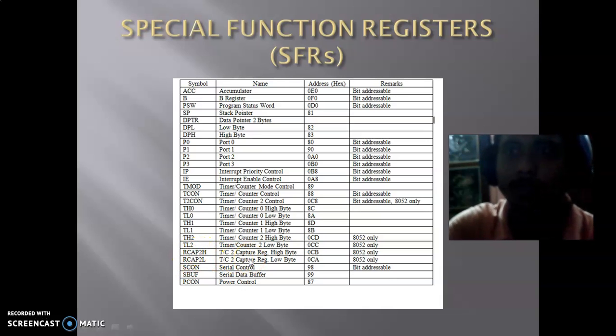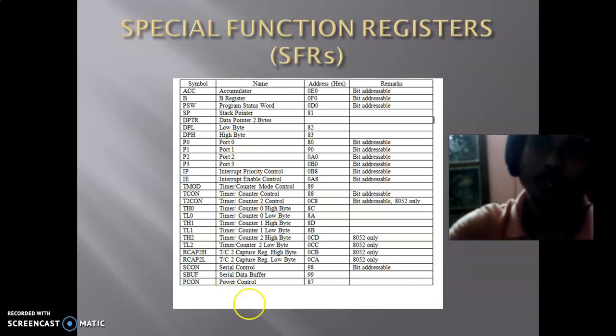RCAP2H, that is the timer counter capture register, high byte, is also used in the 8052 only. And RCAP2L, that is the lower byte, is also used for the 8052 only, but it is not used in the 8051 microcontroller. And we have the SCON register, which is used for serial communication, and that is also bit addressable. And we have the SBUF register, where the serial data is stored after receiving and before transmission. So this is not bit addressable, but 8-bit data can be stored.